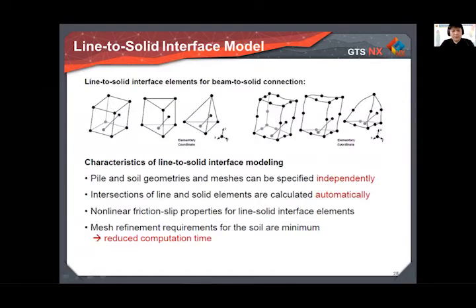Again, the pile and soil geometries and meshes can be specified independently, and the interaction of line and solid elements is calculated automatically. The mesh requirements for the soil are minimal, so finally you don't need to spend much time, and the computation time during the analysis can be reduced.